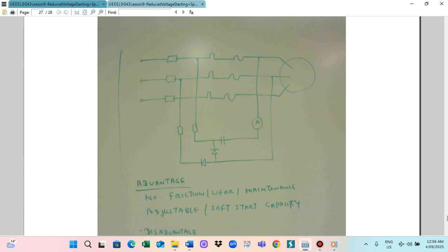So the motor shaft is released and the motor will rotate. As soon as you press stop, the brake will hold the motor shaft. By this we control the electric crane. The brake system is such that when the system is running, it should release so the motor shaft can run. As soon as you stop the motor, it will hold the shaft.